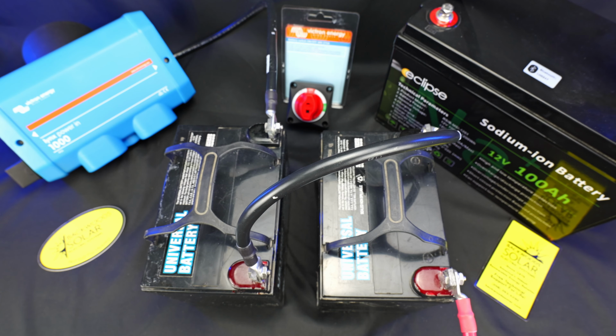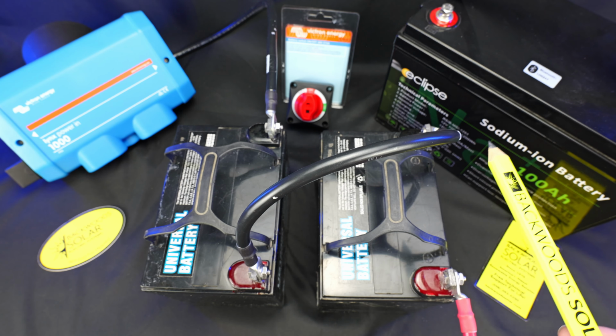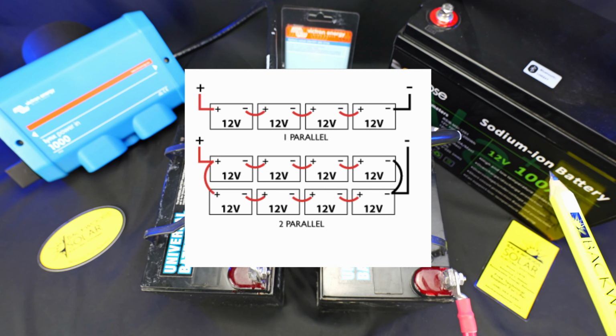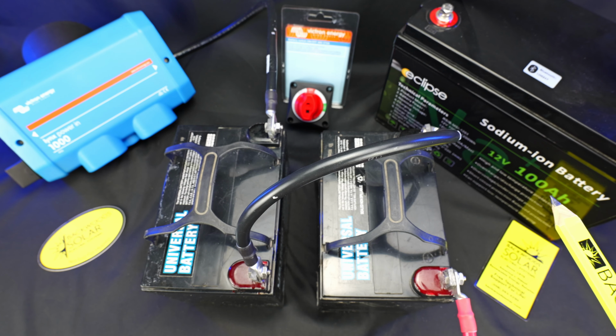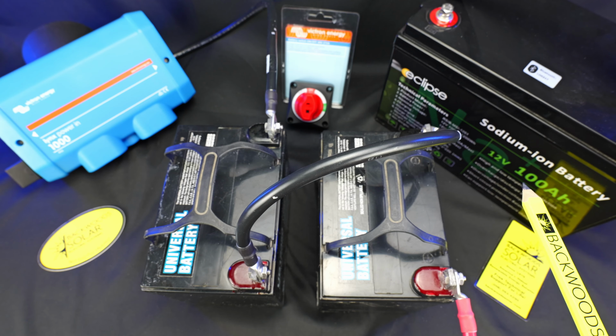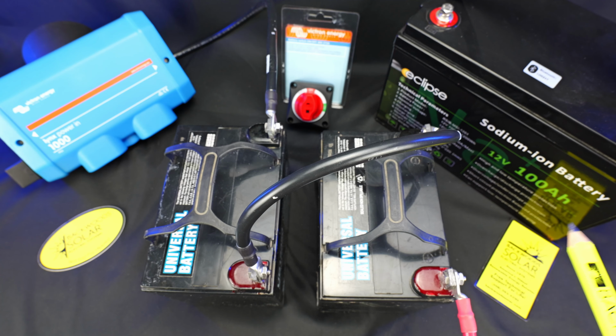When selecting a battery or designing a bank for your application, I do want to make one small note about lithium and sodium batteries. It is really our preference here when purchasing lithium or sodium that you purchase them and utilize them at their design voltage. While a lot of manufacturers do allow, as an example, 12-volt batteries to be put in series in terms of lithium or sodium, I think that takes away one of the biggest advantages of lithium and sodium, especially at higher voltage banks like 24 and 48 volt, is that each battery is at system voltage. So you only need one lithium or sodium battery to keep the system functioning.